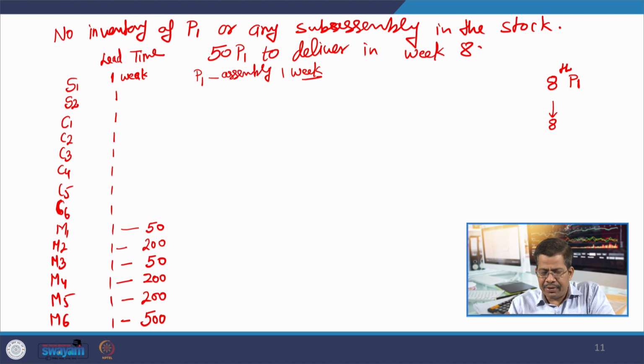So, to deliver in the 8th period, you have to complete the assembly by the 7th period. So, 7th period, assembly, P1. For getting assembly done in the 7th period, you need to get the S1 and S2 delivered to you in the 6th period. So, you will get the delivery of S1 and S2 in the 6th period when you have released the order in the 5th period.